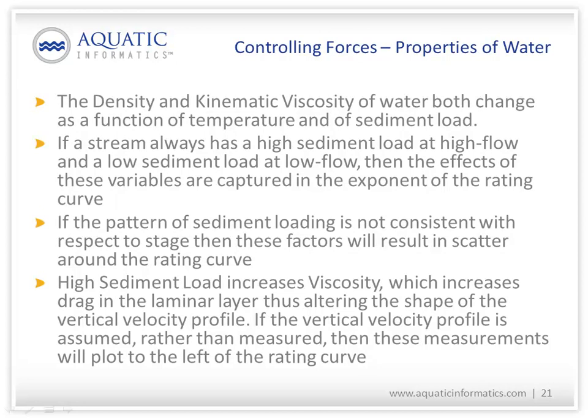The physical properties of water are also considered in the head loss equation. These include density and kinematic viscosity of the water. And these both change as a function of temperature and sediment load. If a stream always has a high sediment load at high flow and a low sediment load at low flow, then you can expect that this change in density with respect to stage is going to be captured in the exponent of the rating curve.